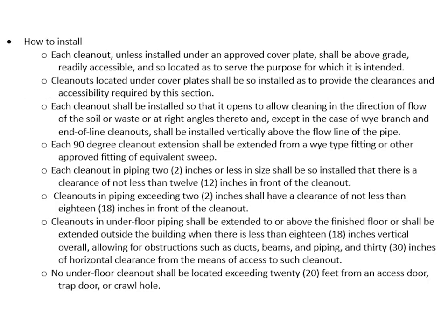How to install. Each cleanout, unless installed under an approved cover plate, shall be above grade, readily accessible, and so located as to serve the purpose for which it is intended. Cleanouts located under cover plates shall be so installed as to provide clearances and accessibilities required by this section. Each cleanout shall be installed so that it opens to allow cleaning in the direction of flow of the soil or waste, or at right angles thereto, and, except in the case of a Y branch and end-of-line cleanouts, shall be installed vertically above the flow line of the pipe.